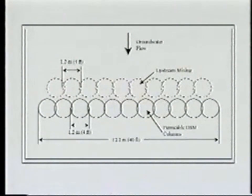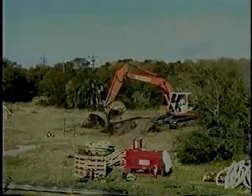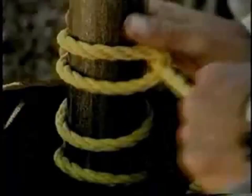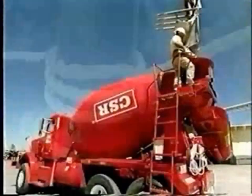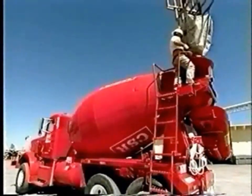Prior to testing, a drilling company is contracted to perform deep soil mixing at the designated site. A vibration tool is used to install each 10-inch diameter steel casing to 40 feet below land surface. Steel casing is now ready to be filled with a gravel-iron mixture. A concrete mixing truck combines a blend of iron and gravel.